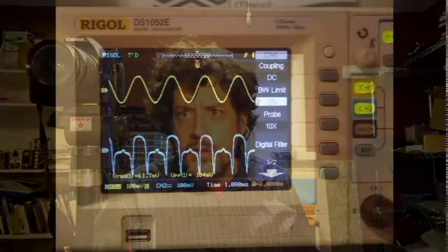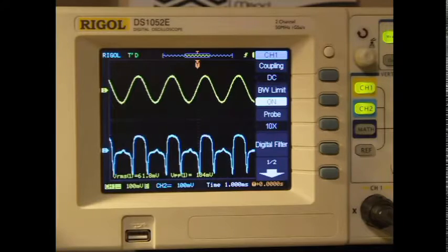So it means I sit here with an oscilloscope and listening, and I try every single germanium diode that goes into an Octomotron, and I pick out the good ones. One thing I have learned to look for, because it sounds kind of cool, is if they're a little bit mismatched. And you can tell they're mismatched because you have one hump that's taller than the other. And when you get a little bit of that mismatch, it just sounds a little more harmonically interesting to me. So I shoot for that.